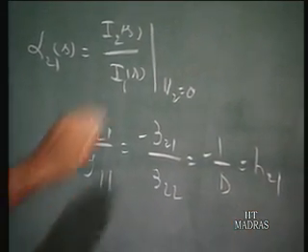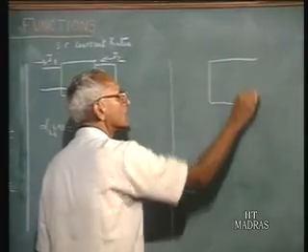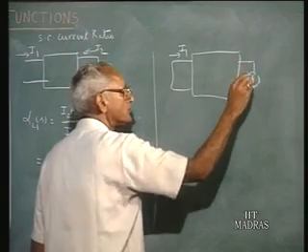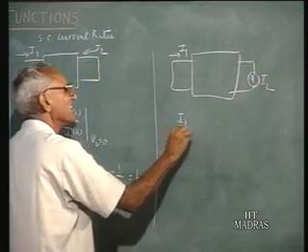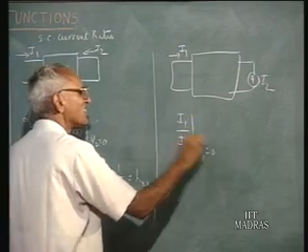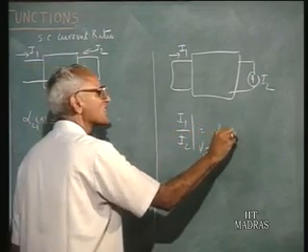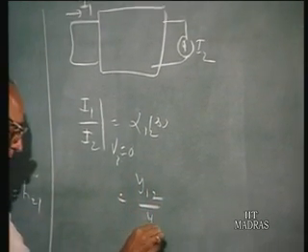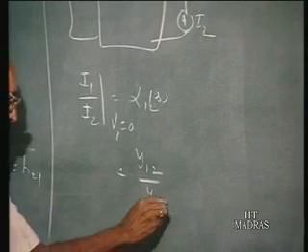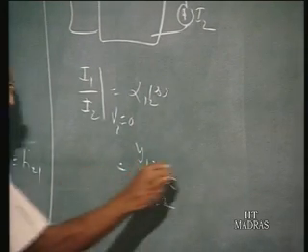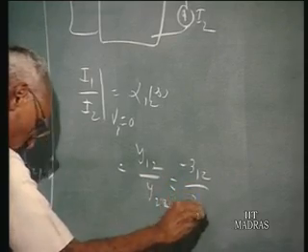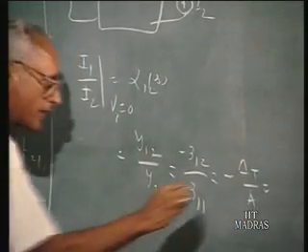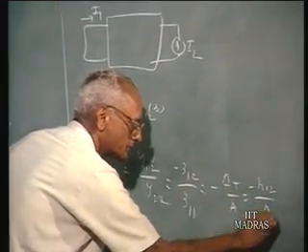And to complete this picture, you might have a situation where you want to find out the ratio of I1 to I2 when V1 is 0. This is alpha 12(s), and this can be shown to be Y12 over Y22, minus Z12 by Z11, equals minus delta T over A, equals minus H12 over delta H.